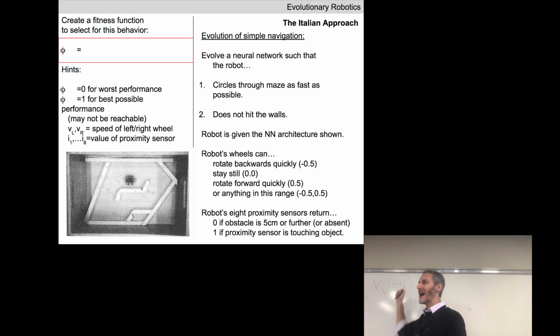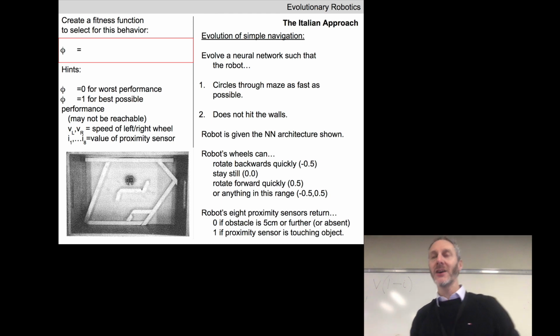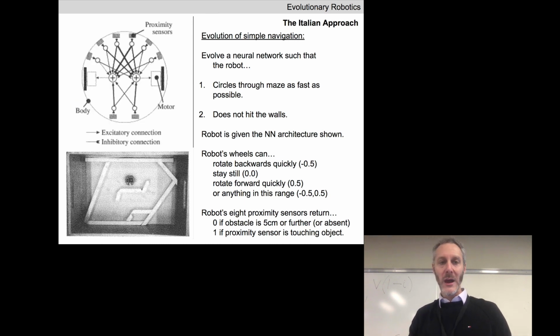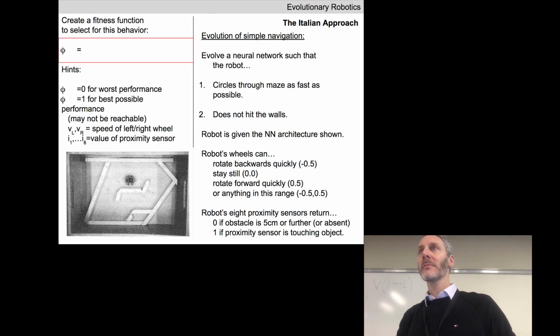So let's talk about I for a moment. How do we combine our I1 through I8 into I? We want it to avoid the walls. Give more weightage to the sensors that are in front. Possibly. Probably you bump head on first. We could weight the ones that are most anterior, or towards the front of the robot. You could average them.